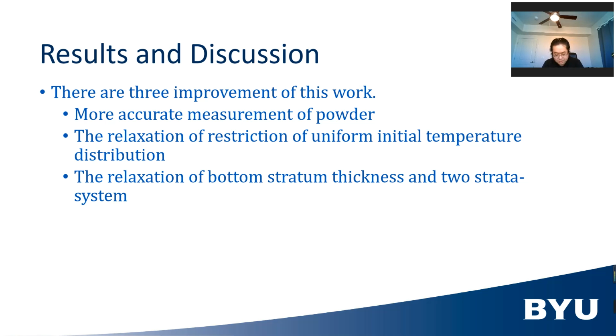Secondly, since the restriction in initial temperature distribution in depth is now relaxed, using superposition of PDE2 and PDE3, we can easily solve the PDE system with free term and initial temperature distribution. This means that we can accurately measure the thermal property of a sample despite the presence of temperature gradient in the sample. This means that the cooling interval between every flash is greatly shortened. And monitoring BJ printing process is now possible. In this case, defective parts can be filtered out before the printing process is finished. This saves time, energy, and material, and we have better control over the BJ printing process.